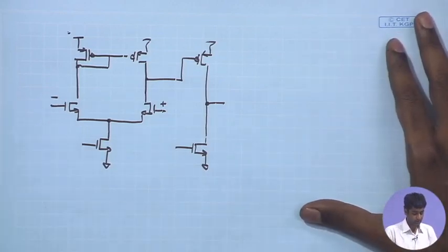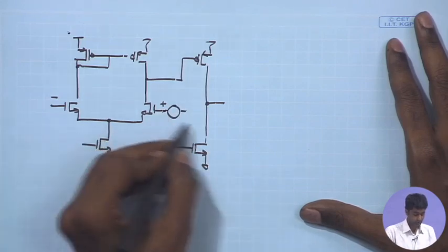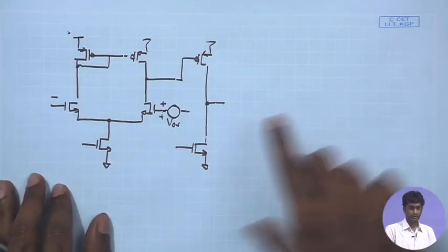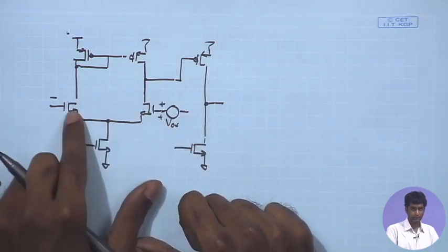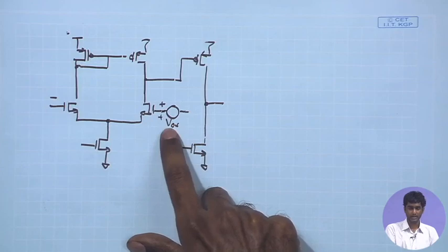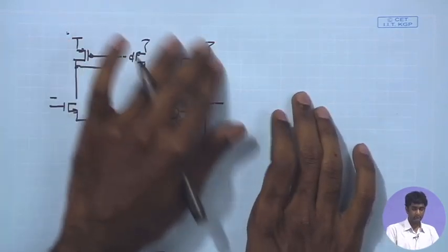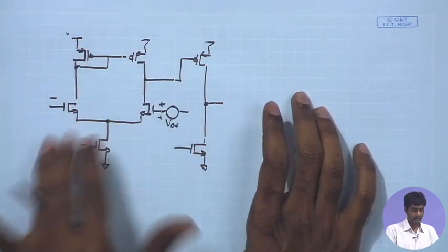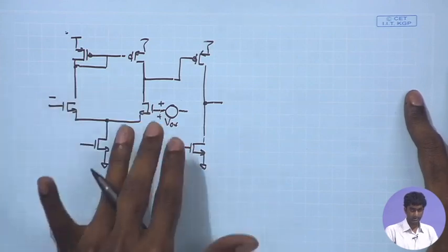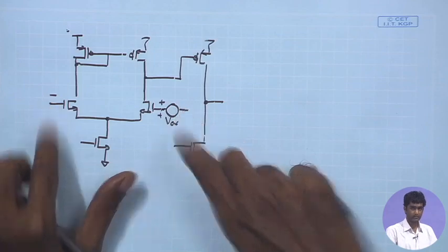So, as we have done earlier, we can start with assigning an offset voltage over here. Suppose we extract the offset voltage from the comparator, whatever is the effect of mismatch in the input pairs and load devices, in the form of an effective offset voltage applied at the gate of the MOSFET. And then we are left with the ideal amplifier. Then we have completely matched NMOS pair and fully matched PMOS pairs.